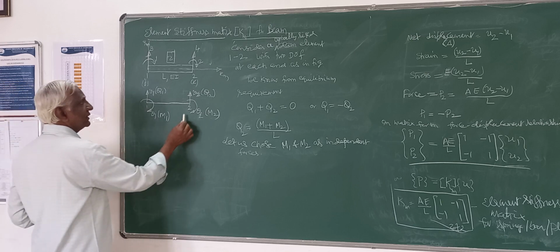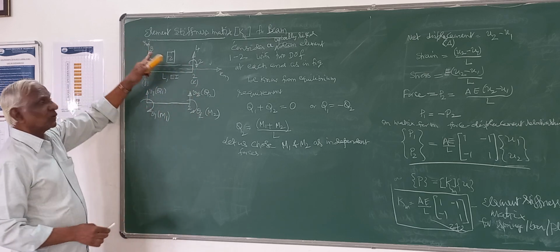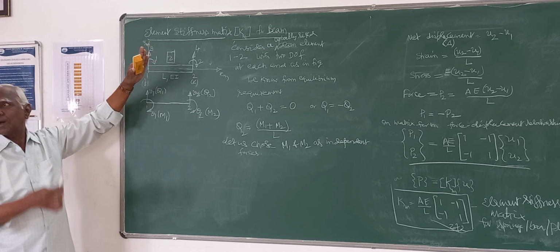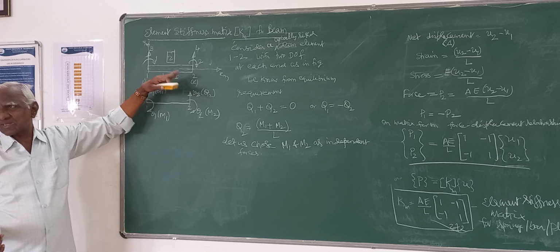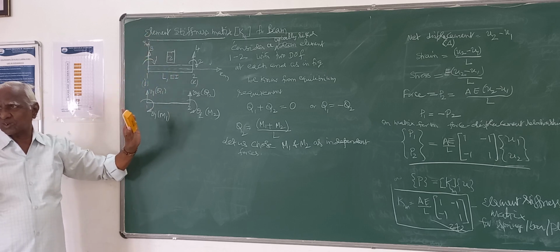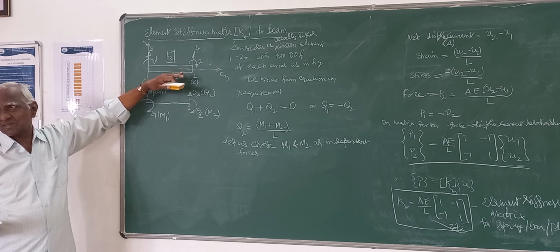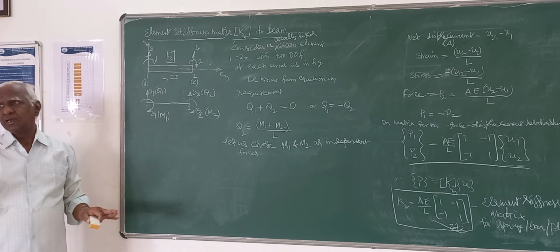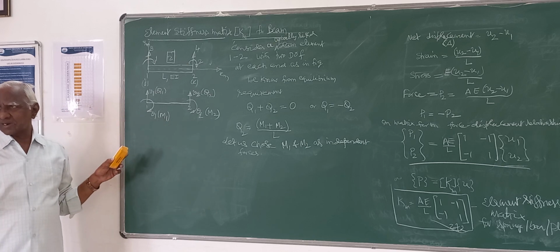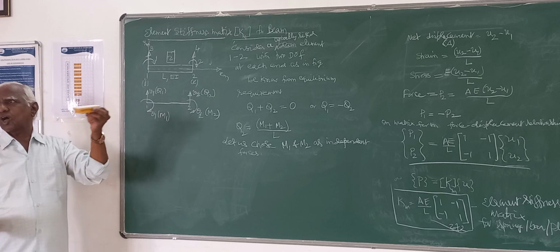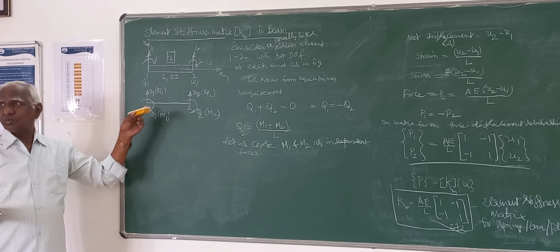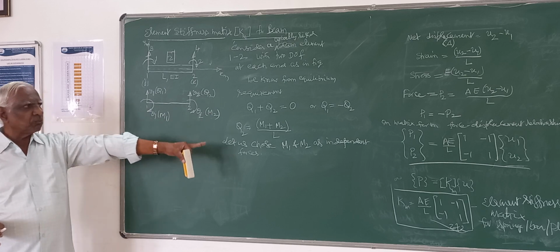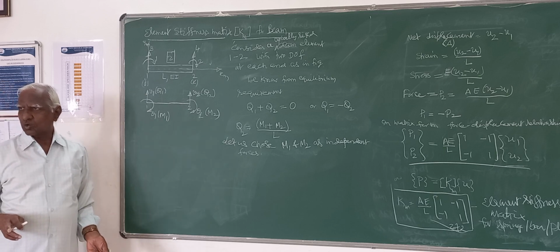If I select this V2, then actually global V2 and this is not the same, because if this beam is inclined, then global V differs. Whereas in this case, we may have taken horizontal, global horizontal coincidence. That's okay, but generally it need not be in all cases. Whereas rotation is always the same for local and global. It is same for all planar structures. The axis normal to the plane, they are same for member as well as global. That's the reason I am selecting M1, M2 as independent forces.